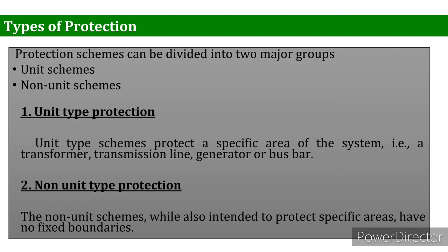I must mention that the unit protection scheme is based on KCL, that is Kirchhoff's current law, that you have studied earlier, which says the sum of the currents entering or leaving any node must be 0. So this is the unit scheme.